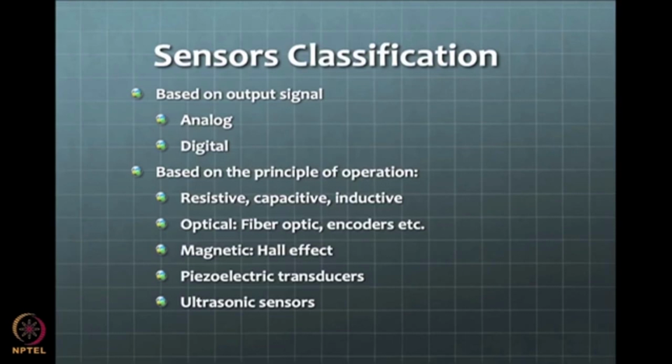When that kind of scenario is there, it has a lot of repercussions on our mechatronic system design. For example, you need to filter noise, or do something about it if it comes in the way of the higher accuracy you require for a given application. So from that perspective, you should look at sensors which have analog as an output.